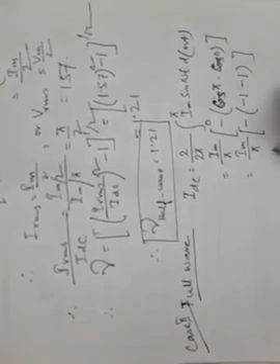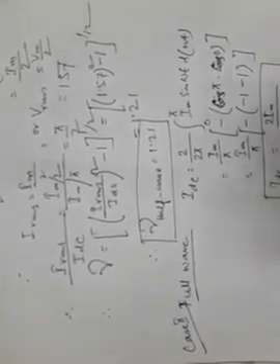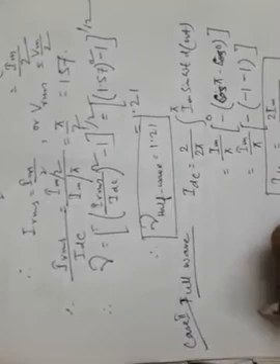So this one will be Im by pi, minus cos pi means minus of minus 1, minus cos 0 means this is 1, so this is minus 2, so this is plus 2, that means 2 Im by pi. So this is IDC for a full wave rectifier, or we can say VDC is also 2 Vm by pi, where m denotes the peak value of voltage or current.